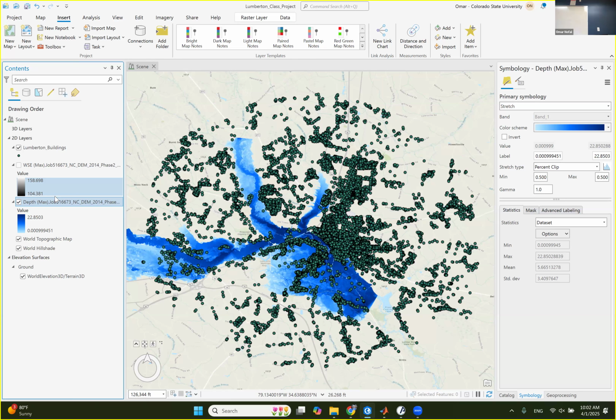All right, let's say we have 2,000 buildings that are going to be exposed to flooding. How can we say that not all of them are applying the mitigation measure? How can I model this? I did it before. The way that I did it, let's say that these are the buildings, and they are from 1, 2, 3 up to building number 2,000. So what I did, I made a uniform distribution from 0 to 1.